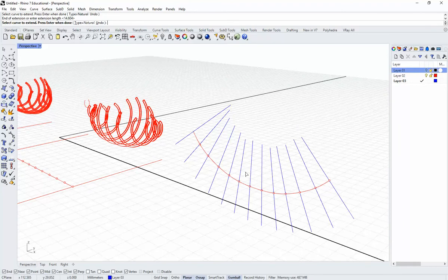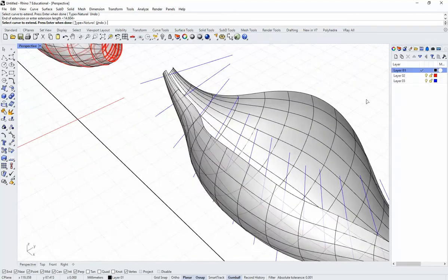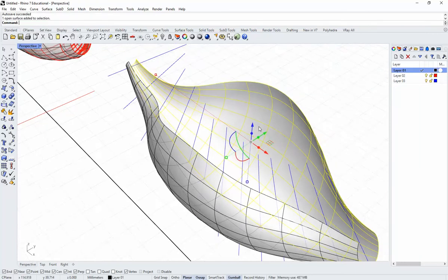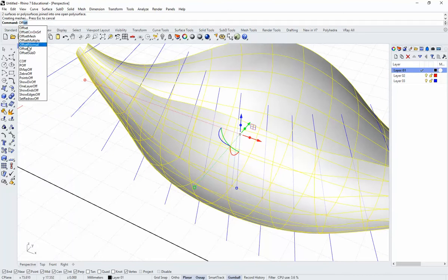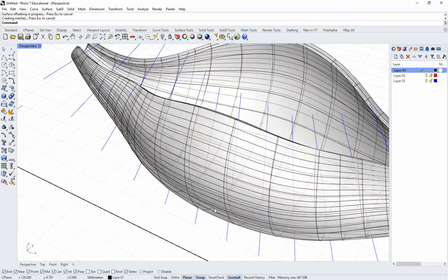So if we do add thickness, which might be a good call here, because it'll be easier to offset the rib so that it has some dimension to it. Yeah, we're going to need to extend that. So let's go ahead and start this process now. Let's go back into that layer, and then we're going to offset this surface like we did before. I'll select both of these and join them. Offset this surface outward, so I'm going to make sure they're flipped. Distance 1, fine. Solid, yes, sure, and then go ahead and let that run.